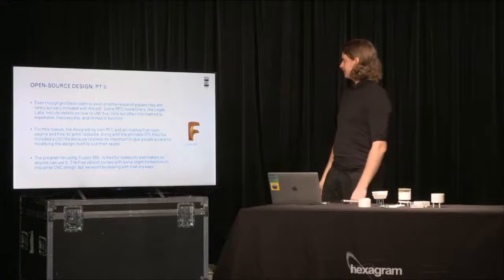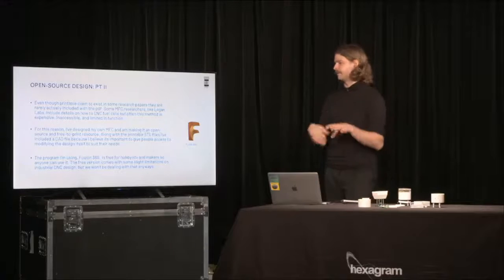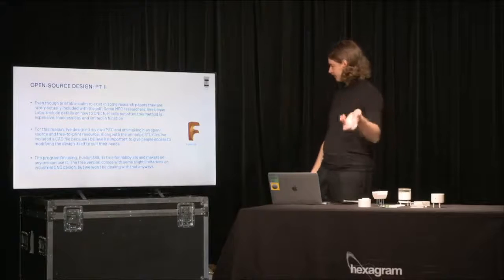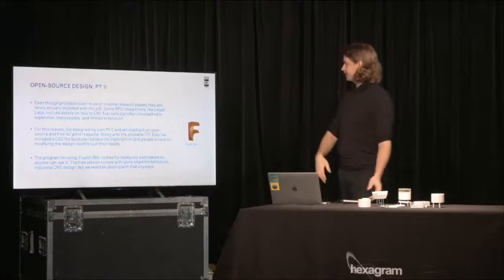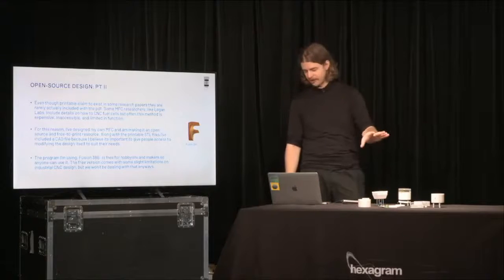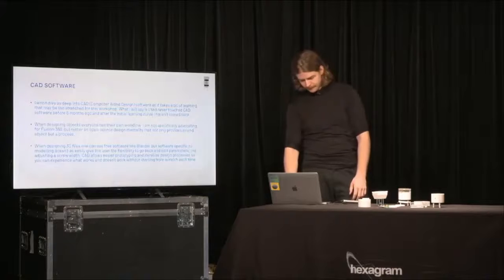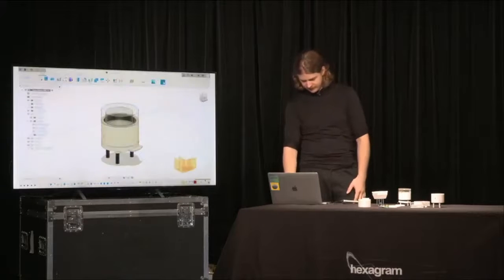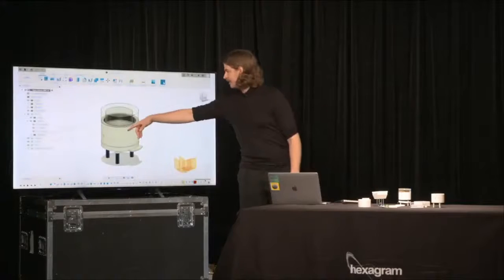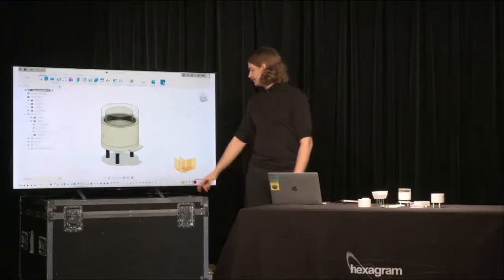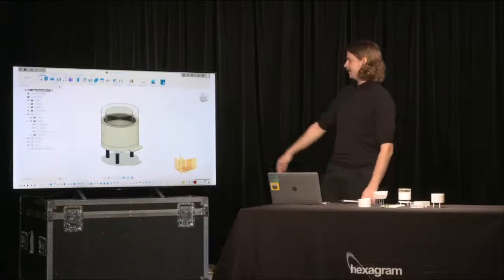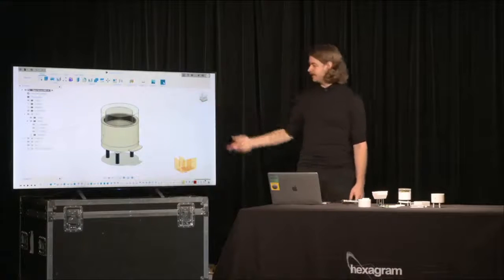It essentially lets you design the cell kind of like in a 3D program, but you can go back to steps and modify your screw size, your hole size. You can delete objects, import objects, etc. It's much more accessible for when you have many different parts. So this is the software. Again, you have all the parts on the side, and you can go back in the timeline and change things very easily. You can import object by object to print.